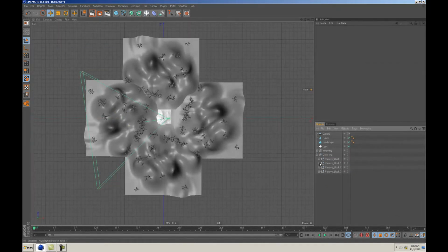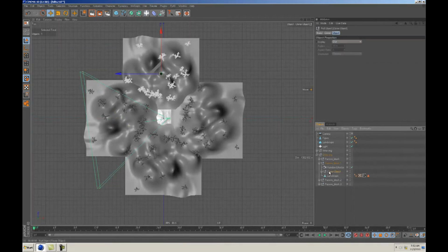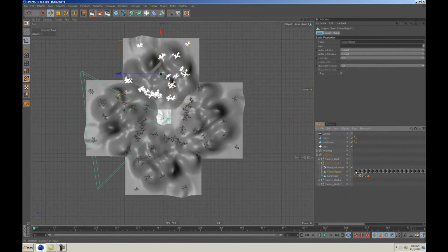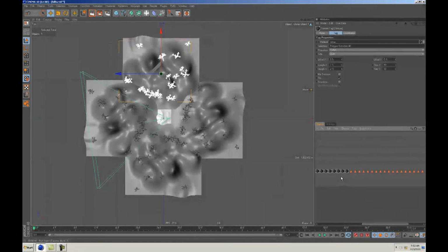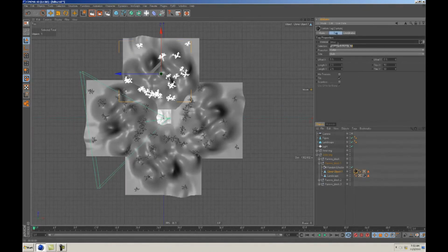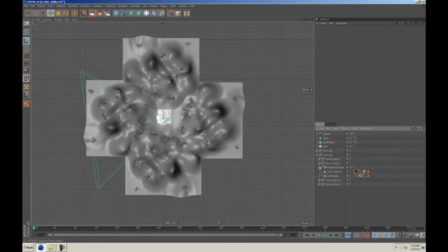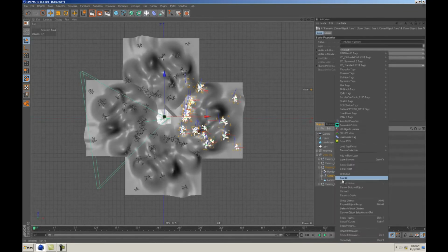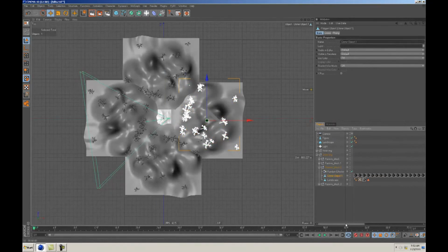We can get rid of that. So now this is just kind of clean up. Select children, connect plus delete, because actually all these tags take up memory too. So if you're really trying to optimize your scene, and this may seem super rough to some people, like, what, you're just randomly going in here and deleting stuff and connecting it without even looking at it? And this is kind of the way I work.